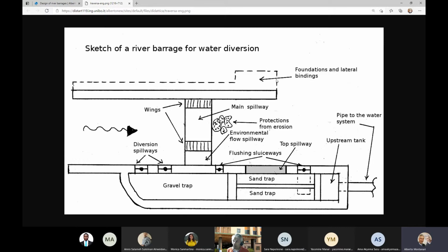It is nice because it's something curious, the fact that pipe flow allows you to save energy when you have a lot of energy, but it is more expensive in terms of energy when the downstream slope is very mild. So if you have a downstream slope that is very mild, it's not convenient to use pipe flow. It's cheaper in terms of energy to use the open channel flow.